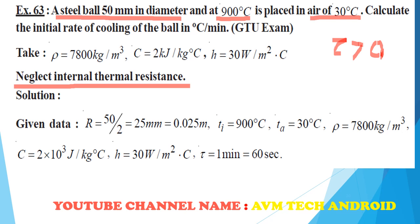The radius is 25 mm, so we have to convert that into meter. Initial temperature is 900, surrounding fluid temperature is 30, density is 7800 kg per meter cube, specific heat we have to convert into joule per kilogram degree Celsius, the convection heat transfer coefficient is given, and time is 1 minute, that is 60 seconds. So friend, this is a very simple case,